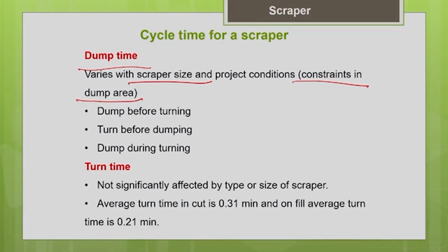Now, we are discussing the dumping time. You can see that there are different ways to dump in a project site. Everything depends upon your project site constraints. Sometimes your scraper will dump before turning. Before turning itself it will dump, and this is a very safe way, because if it turns in a loaded condition, it is not safe for the scraper. So, this is the best way, dump before turning.